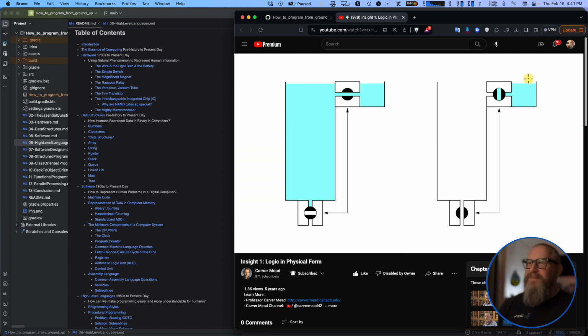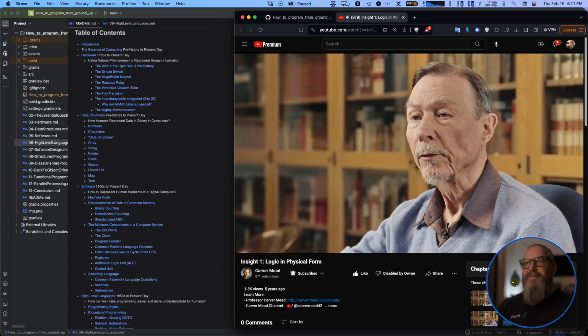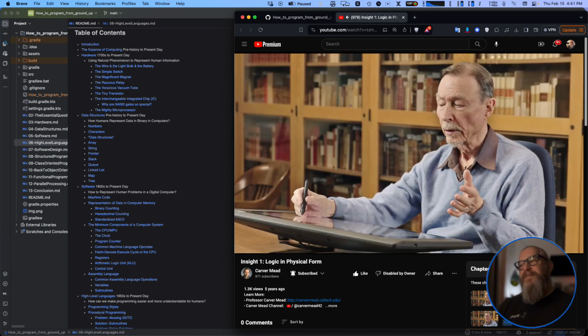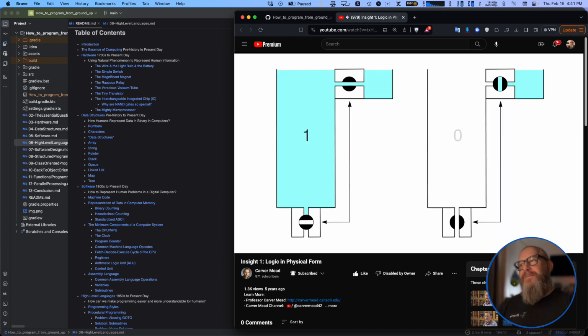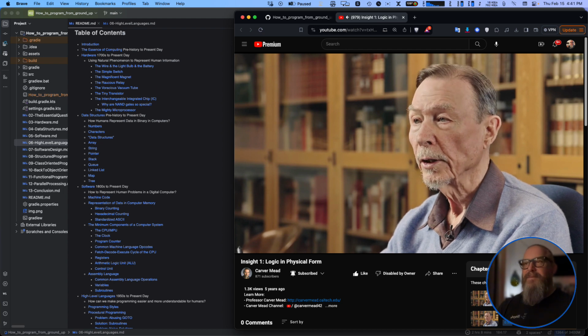And it takes energy. The water up here in the trough is at a higher level than the water in the gutter that we're finished with. So it takes energy to pump that water down below up above, where it can now be used to process more digital 1s. And every time we make a transition between a 1 and a 0, or between a 0 and a 1, we lose energy. We lose the energy of the water in the trough when we fill the tank with it, and we lose the energy of the water in the tank when we let it out into the gutter. So it takes energy to make a transition between a logical 1 and a logical 0.